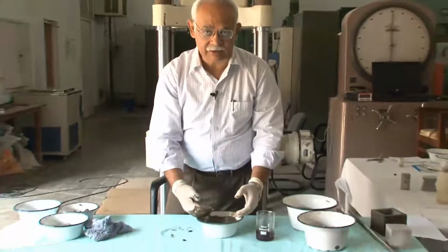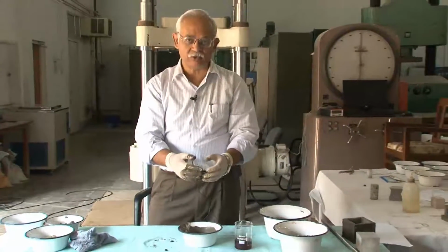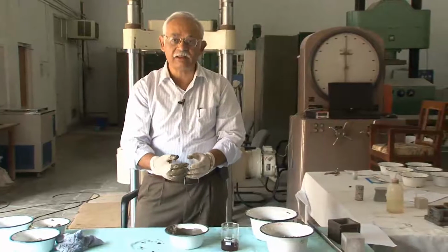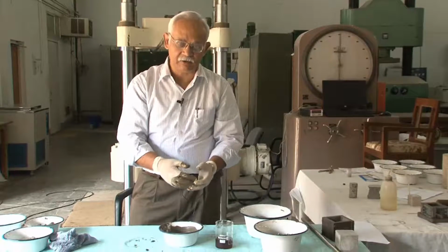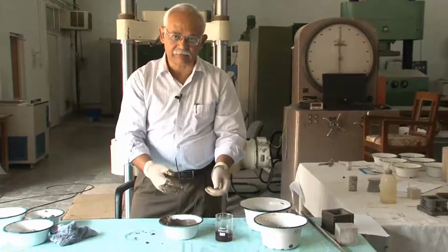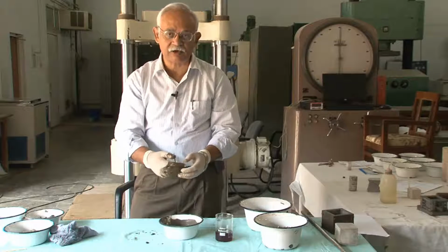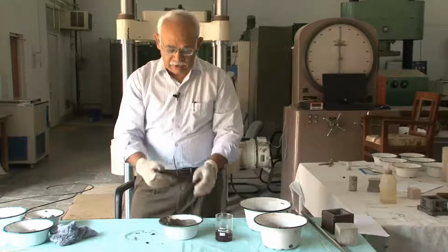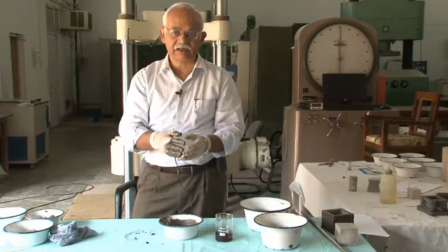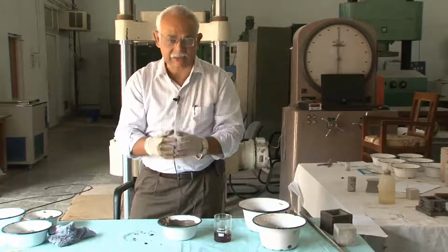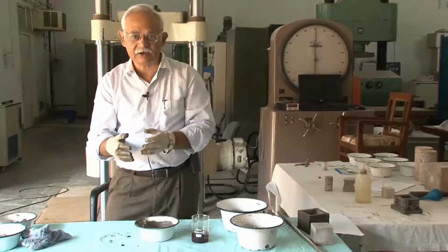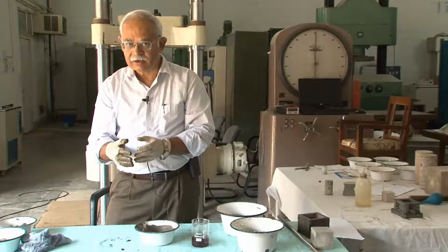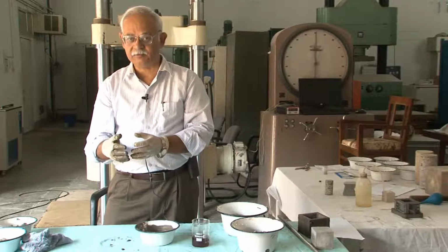What we have seen in this experiment is this chemical admixture being used to increase the consistency or make the paste flowable. If we turn the observations the other way around, we can use this chemical admixture to actually reduce the amount of water required for a given consistency. And now, the consistency of this paste is the critical factor when it comes to the final consistency of the concrete. As we shall see, the consistency of that paste changes as sand is added and it becomes mortar, and then coarse aggregate is added and it becomes concrete.